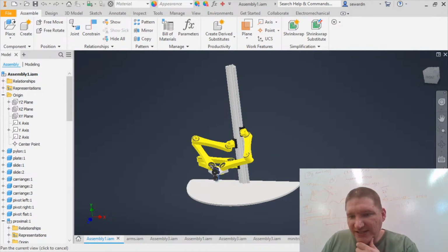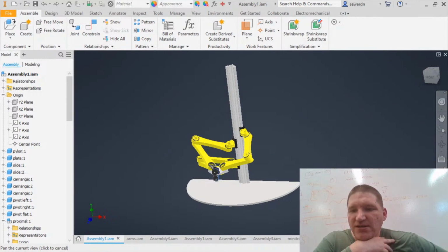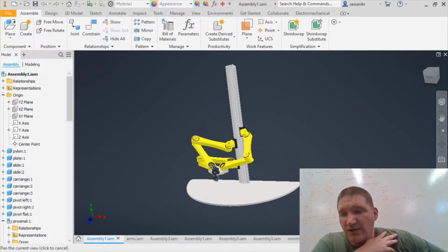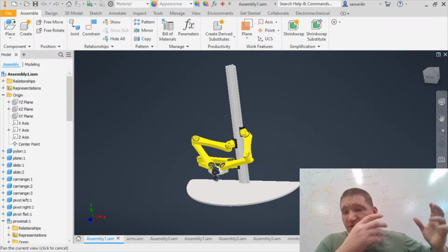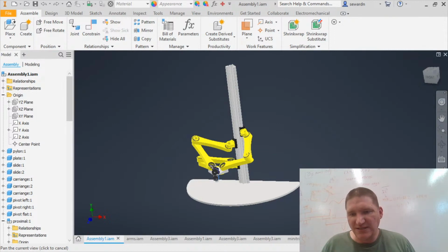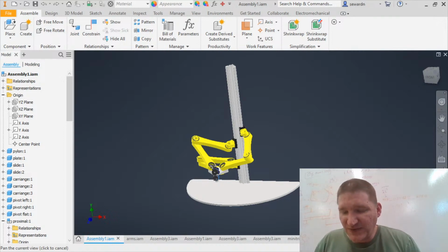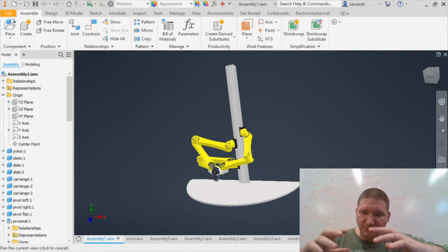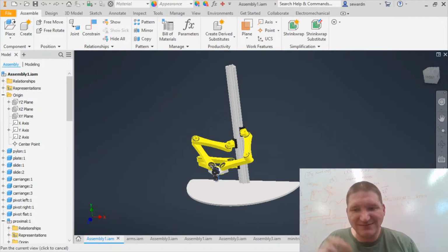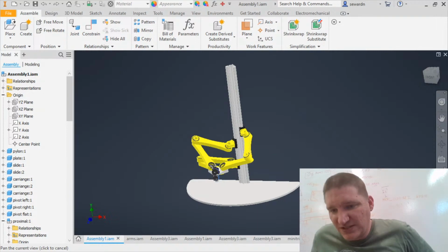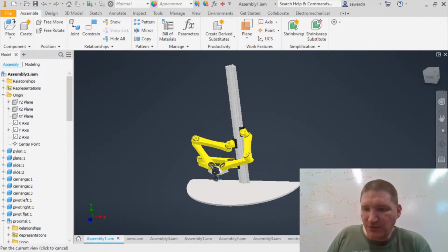Tommy Thorne asked, would there be a significant twisting force on the monorail? Yeah, not significant, not more than a rail could handle for sure with what I'm going to build it for. But you should bolt it down. Anything that long, on the order of meters, even if it's made out of metal, is pretty twisty. If you do the calculations, it doesn't take much to get a little bit of deflection. They can handle the forces, but would it bend down and cause problems in positioning? I don't think so, not a whole lot, but it would be a factor, so might as well bolt it down and not make it a problem.